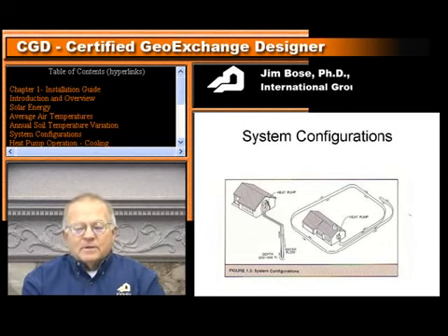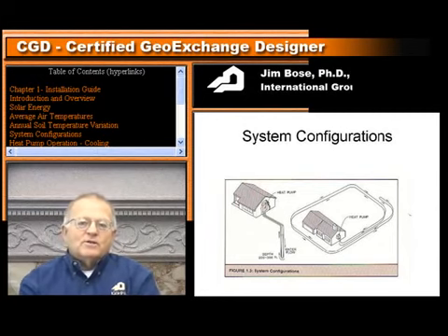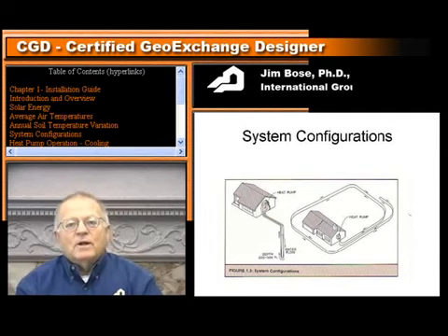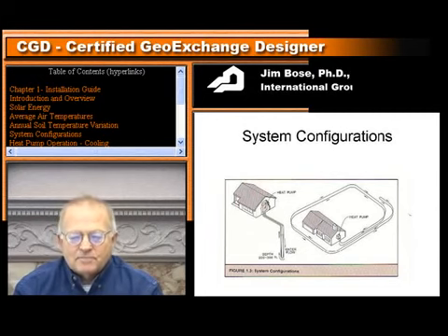If the soil has easy trenching characteristics, and you find a lot of trenchers in your area, you might be going horizontal. Whether you put 1 pipe in each trench, 4 pipes, 6 pipes, or 8 pipes will all depend upon an economic study of what it takes to bury pipe underground in your particular location.